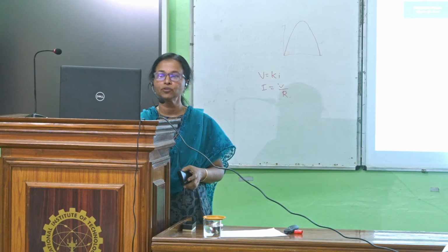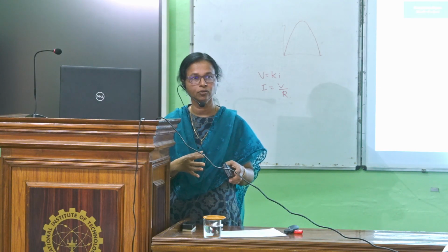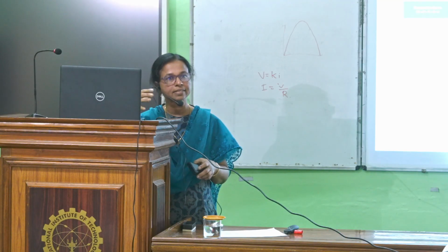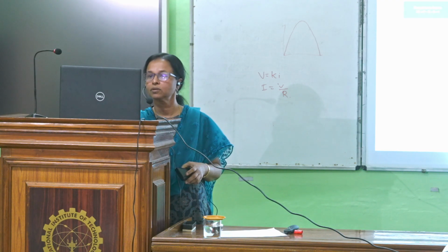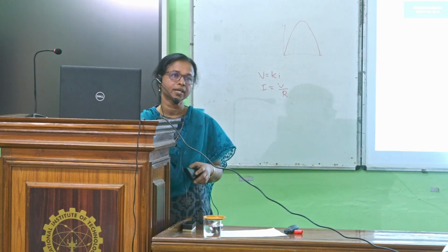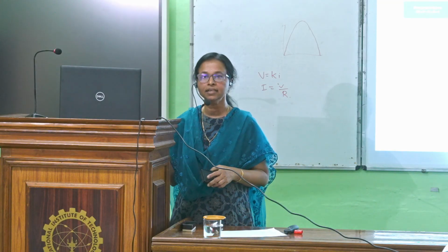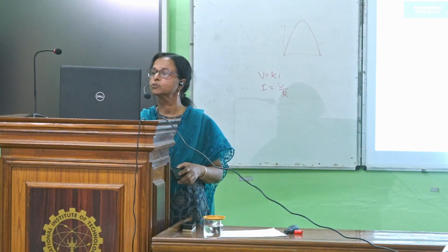And then you have to do this for each sub-basin. Then from each sub-basin you have to route, and in the reaches there will again be losses and gains. That you should also consider, and then finally you can get the final discharge. So this is the process of hydrologic modeling in HMS. Again here for routing methods there are different methods, and for loss and gain there are different methods. So this is the basis of hydrologic modeling in HMS.